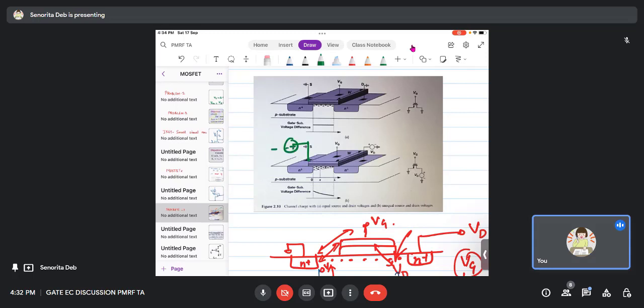and grounded this, right? These are basically symmetric terminals. In a BJT, the emitter, collector and base are differently doped, so it is an asymmetric device, but the MOSFET is a symmetric device. It is equally doped. So depending on where I put the potential, the current will now be in this direction, because now this has become drain and this has become source. This all comes from the MOSFET's construction.